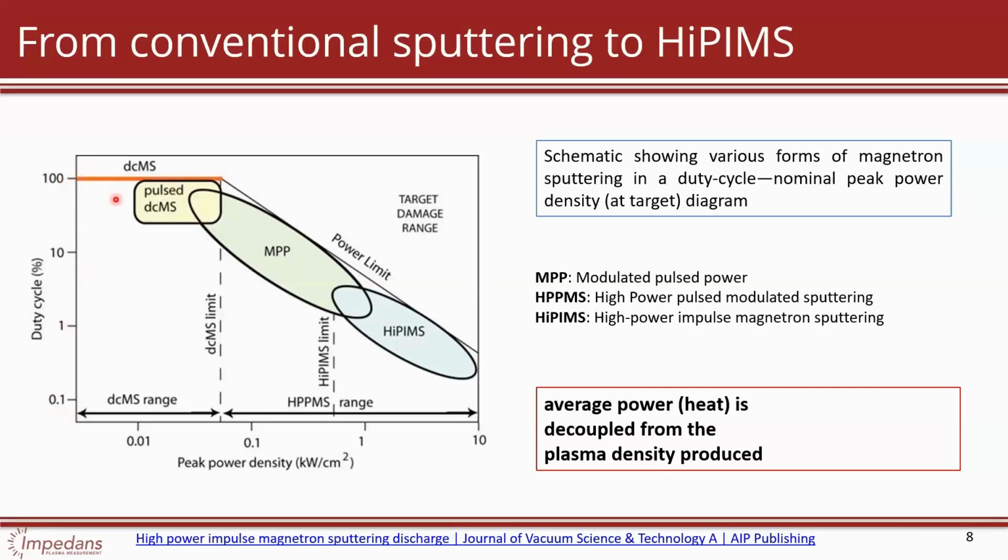the duty cycle sort of limits the power density that you can achieve, right? So in order to make a more and more intense plasma, so if you want to have faster sputtering rates, so you coat the tool quicker and make a thick layer quicker or whatever, you want to have higher sputtering rates. And then if you're trying to make a particularly hard coating, you want very high ionization rates. So that means you want really high power density locally.